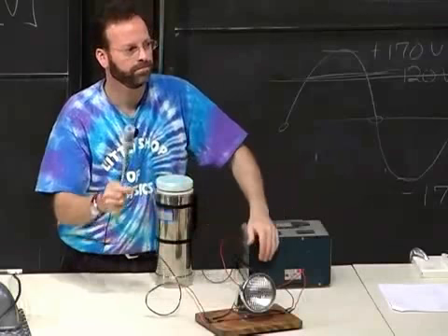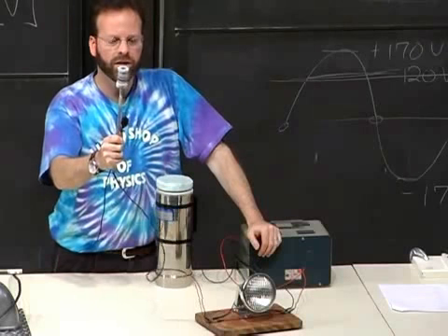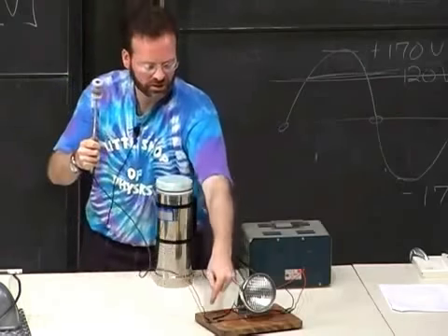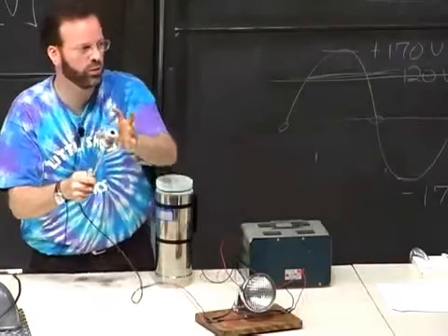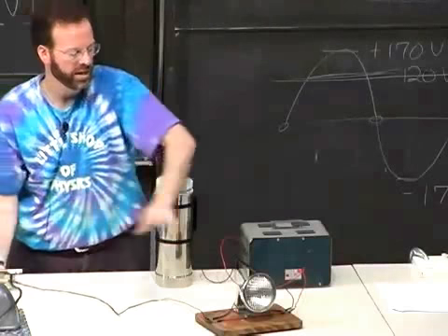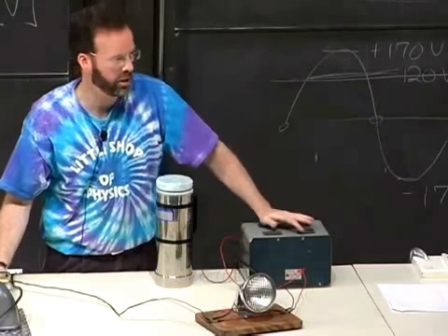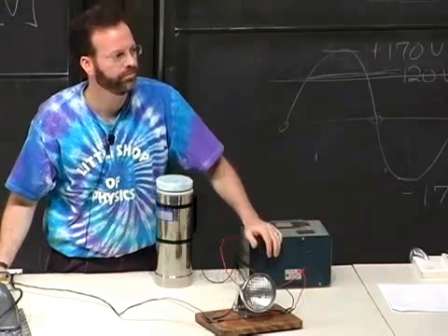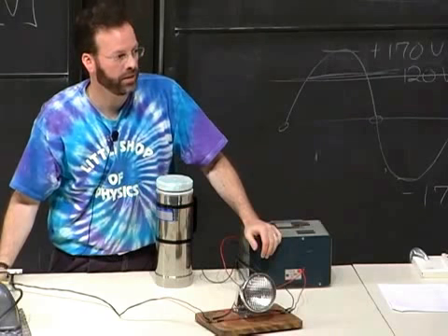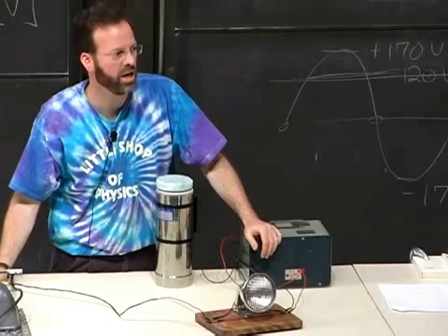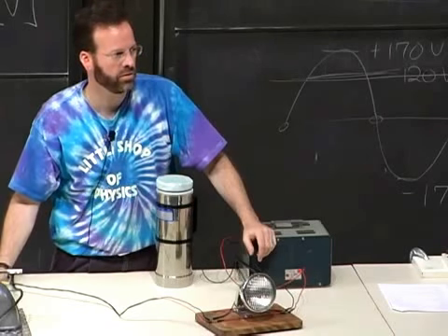Okay, but what would happen if you didn't have the resistor at all? Then if I just removed this and shorted across it, so there was still a complete path, I removed the resistance from the circuit, and now it's just this resistance. There'd be less resistance total, and probably enough charge would flow and it would light. Would it blow up? It might. Yes. I'm not going to try it for that reason, because I'd measure this resistance first.